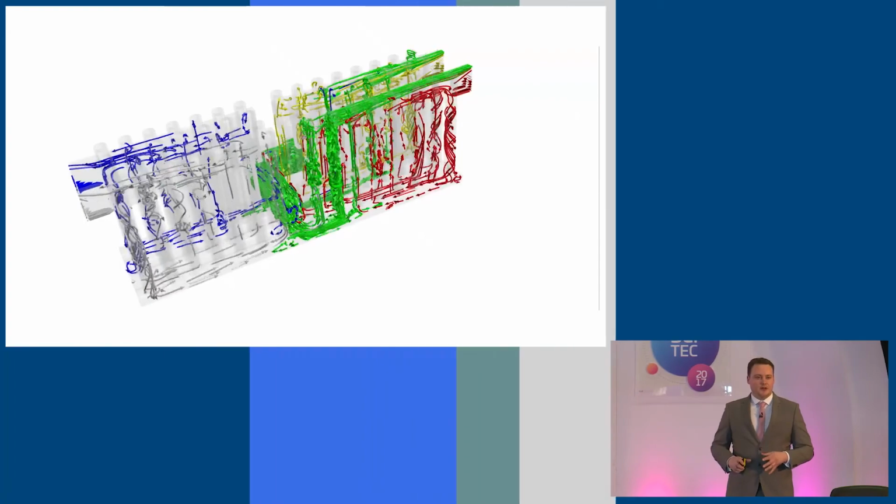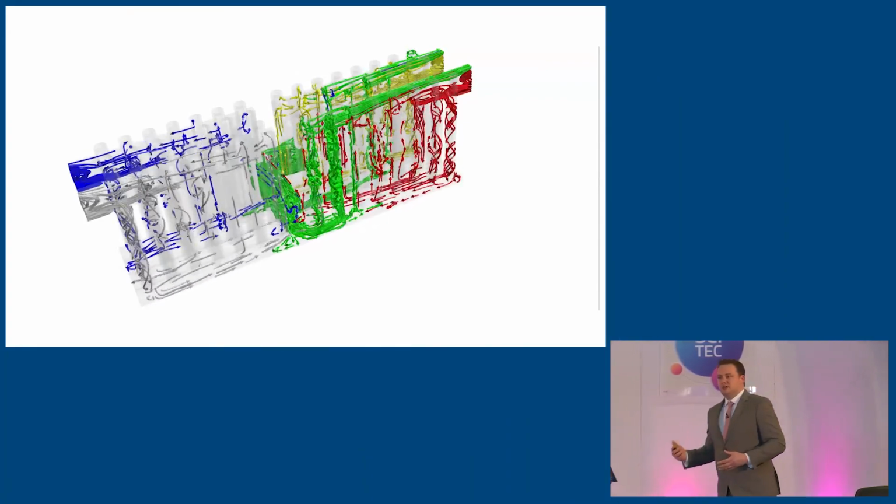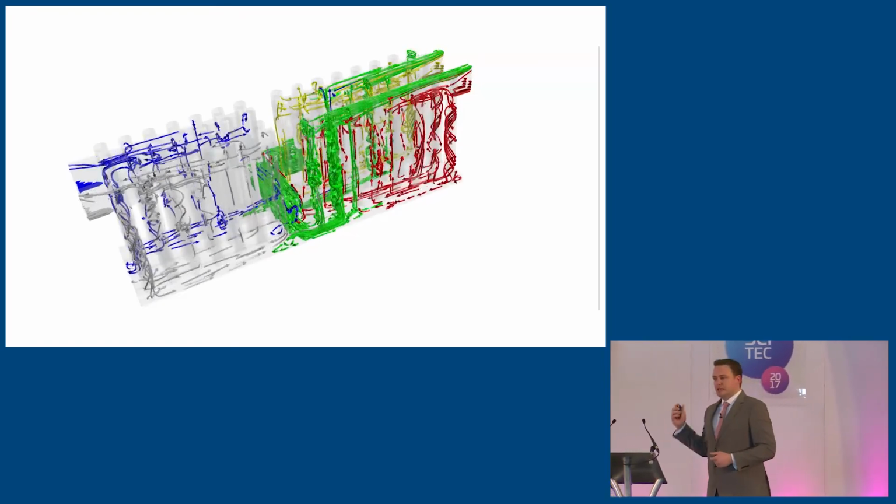If we crank down the inlet flow rate, what we're doing here is simulating a loss of cooling, so if there's a power cut on site or some kind of accident on site, what we find is really interesting. This demonstrates the power of the modelling, because we can't simulate this using hand calculations or experiments. It's too complex, it's too big. But what the modelling shows us is that if you turn off the ventilation or crank it right down so there's hardly any flow entering the store, the buoyancy forces are enough to suck in air from outside. So what that means is even if you have a loss of cooling, this store remains cool and it remains safe. So that's great for our customer.